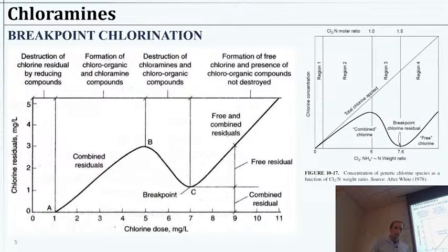Okay, this means that if we want to achieve chlorination for drinking or wastewater treatment, we have to handle a few things. And calling back to what we were talking about on Tuesday, first there are some residuals or some chlorine demanding substances that will exert a rather instant demand and react with our chlorine before we can make use of it for anything meaningful.